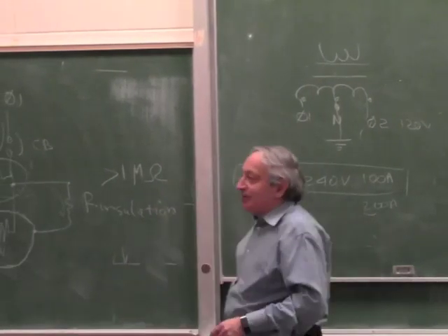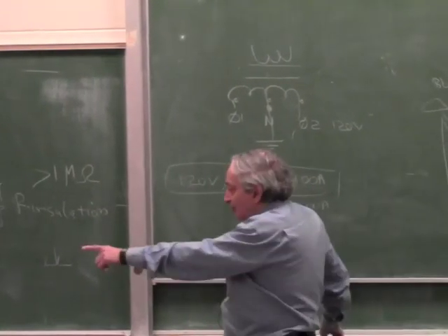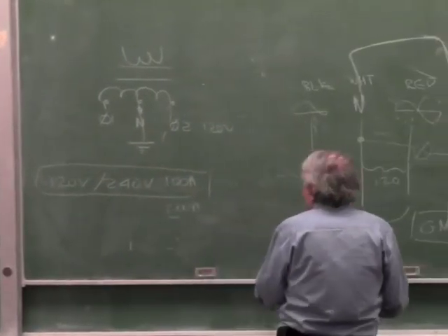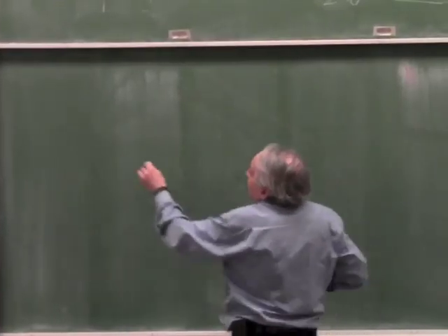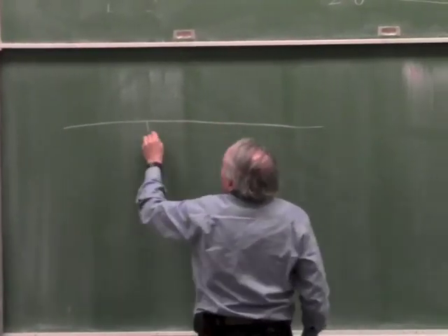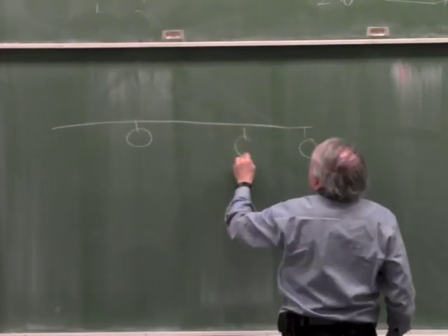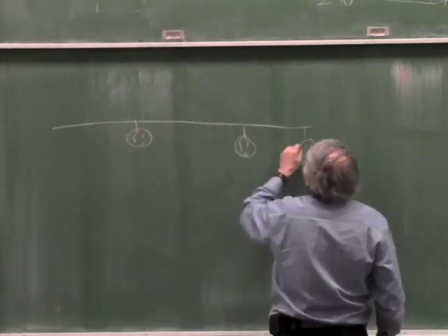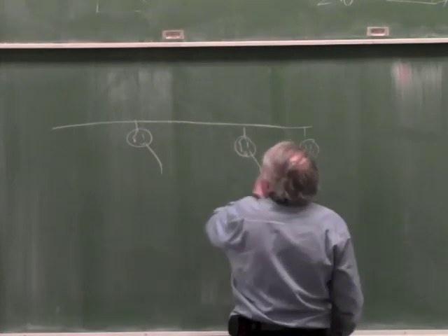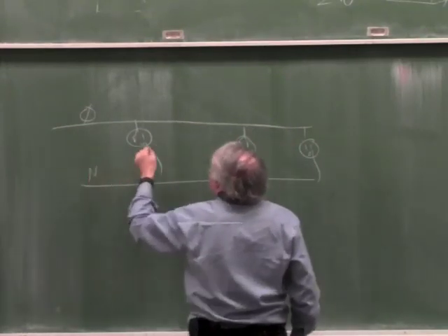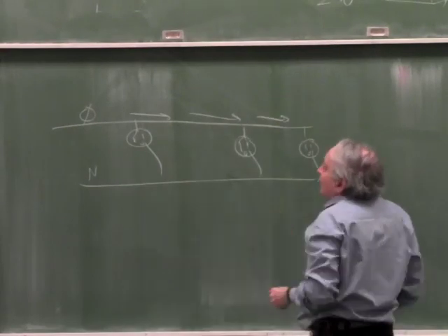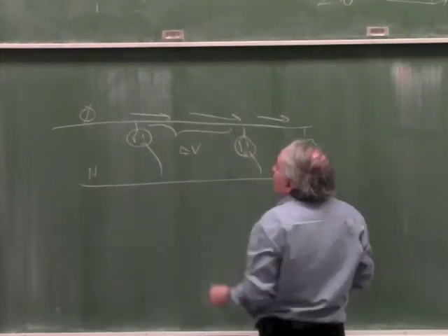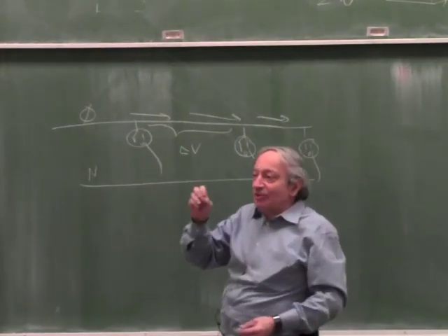So I would expect, if I measure the phase between two outlets or the neutral, I would see a small difference. Because the reason I'd expect this, because in a house, if the phase comes in, there's many outlets, and the phase is connected to one side and the neutral is connected to the other side. This is phase and this is neutral, and there is some current flowing which could be quite heavy, so there will be some voltage drops. So this will be delta V. So I would expect that between outlets I can see small delta V's.